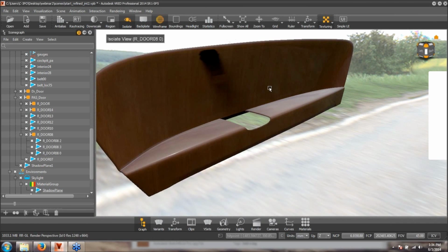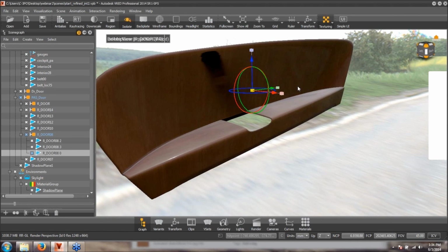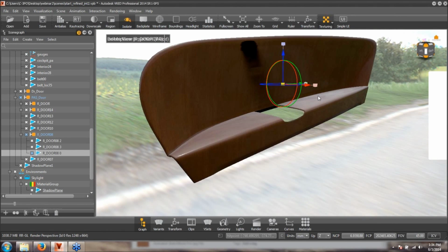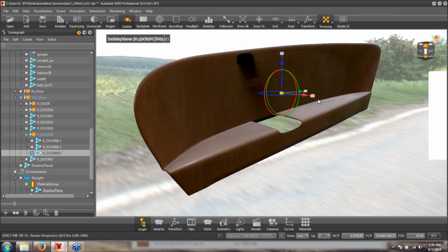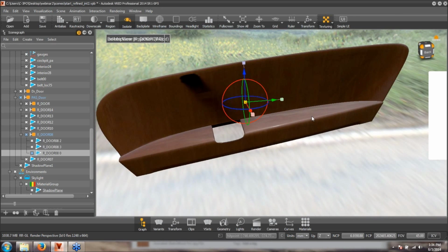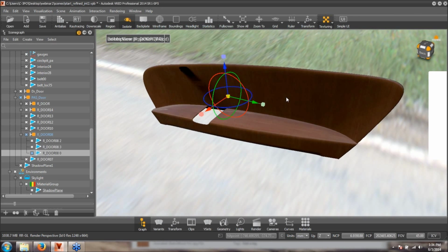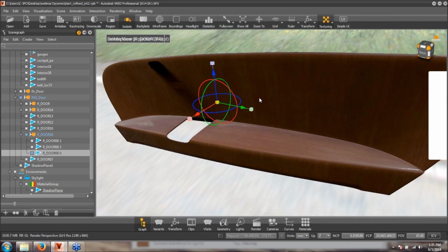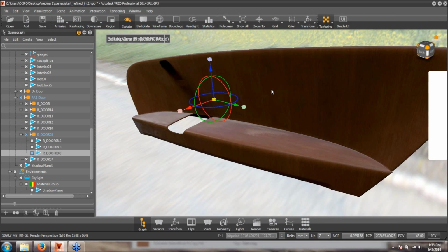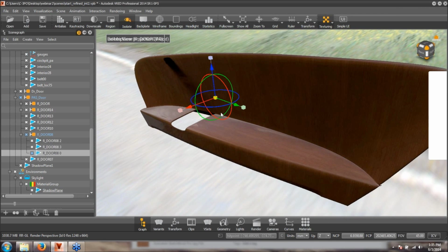Turn on texturing, and you can scale it up. Now the nice thing about triplanars is if you have a complicated surface with different faces facing different directions, then you can independently control the direction that the texture lays on each surface. And keep in mind, just like the other Autodesk products, red is always X, green is always Y, and blue is always your Z axis.